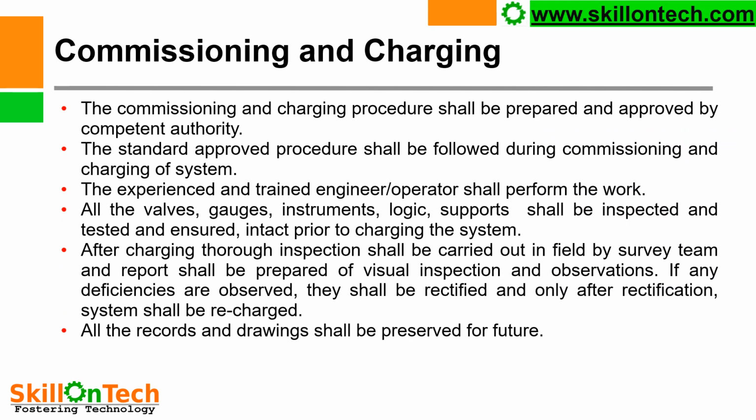Commissioning and charging. The commissioning and charging procedure shall be prepared and approved by a competent authority. The standard approved procedure shall be followed during commissioning and charging of the system. An experienced and trained engineer or operator shall perform the work. All the valves, gauges, instruments, logic, and supports shall be inspected and tested and ensured intact prior to charging the system.